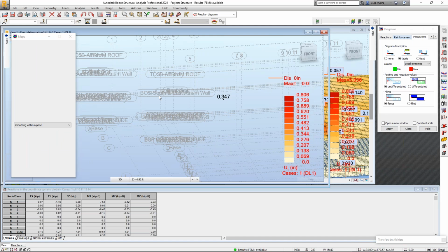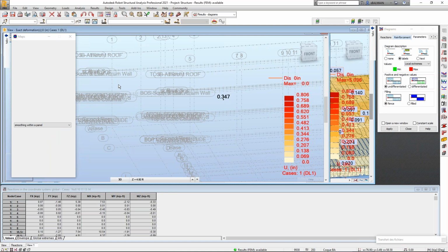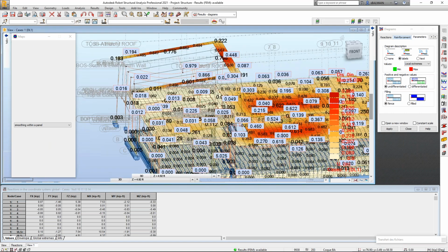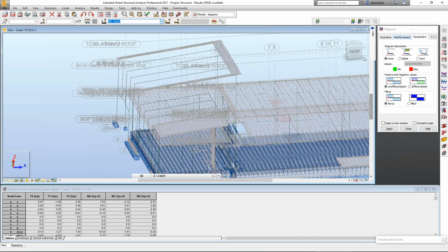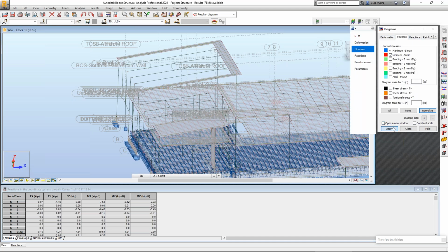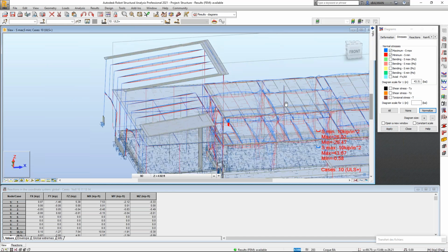Okay. So once I've looked at my displacement, and if it's correct, it means that my supports are correct and everything is quite fine. I will be interested in my global stress. So for the beam here, I will go on the maximum and slow bending. And maybe I won't look at everything. I will go for some labels here.